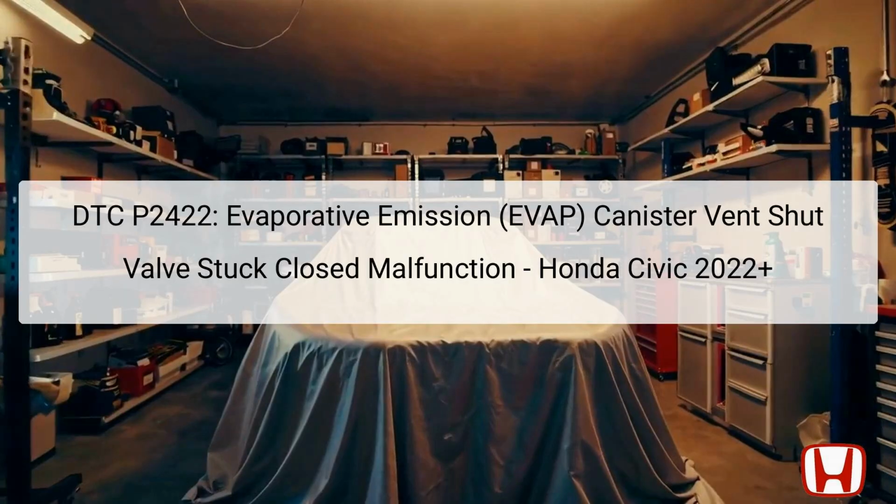The diagnostic trouble code DTC P2422 refers to a malfunction in the EVAP canister vent shut valve of your 2022 Honda Civic. This valve's primary function is to control the flow of fuel vapors from the fuel tank to the EVAP canister, storing them until they can be safely burned in the engine. If the valve becomes stuck closed due to various potential faults, the Powertrain Control Module, PCM, detects an abnormal FTP sensor output value, triggering this specific DTC.